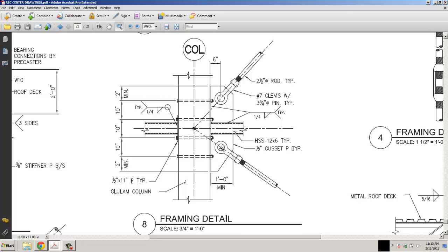And that has these bolts going through that hook on to the turnbuckles and the rods. And it just shows a typical bolted and welded connection on how these things are put together. So it's kind of interesting, especially doing some forensic look. If I have a project I need to do in this building 10 years later, I can pull up these plans and see how it was put together originally on things that are no longer visible from the outside.